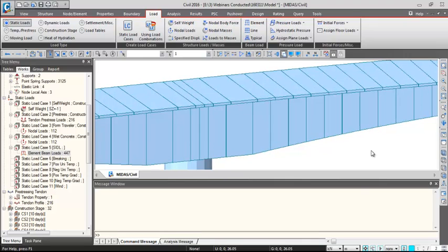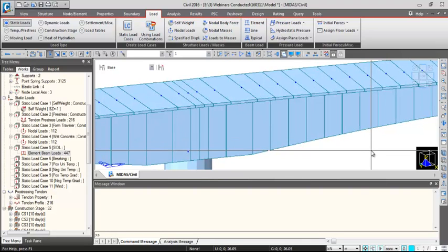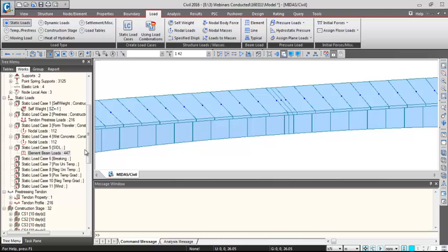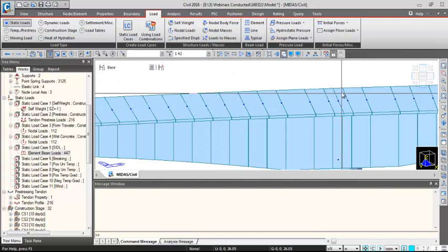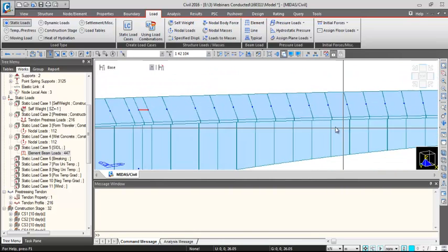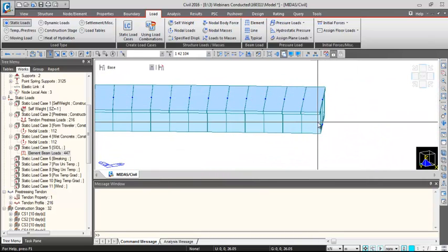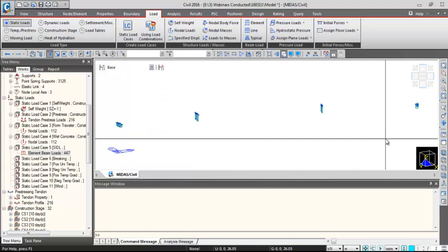So we are going to apply this nodal load on the I node of the element. This is my central element, so I'll select this one because I want to apply load over here, that is the I node. Similarly, this element over here, and in this case I can't apply on the I node, I'll have to apply on the J node, but I'll just select this element. Okay, and activate. So the relevant elements have been activated. This is for ease of application of the loading.